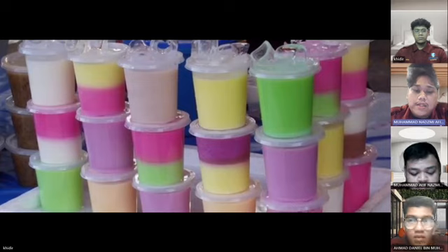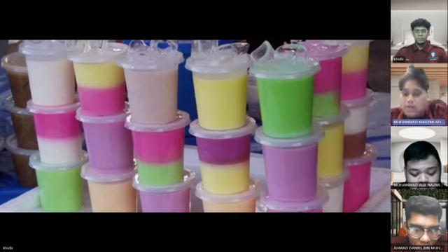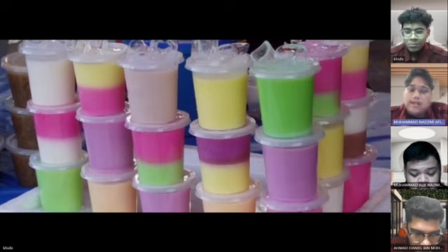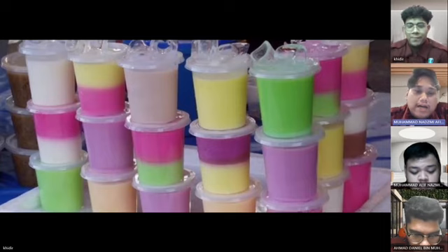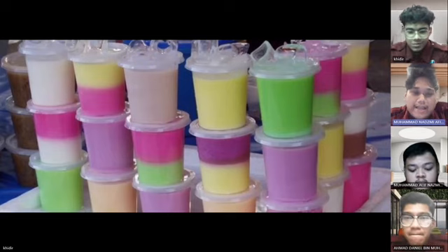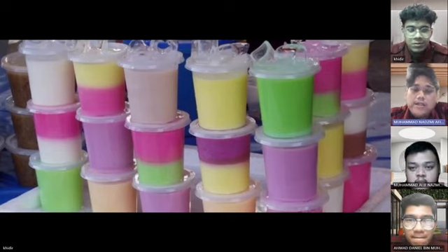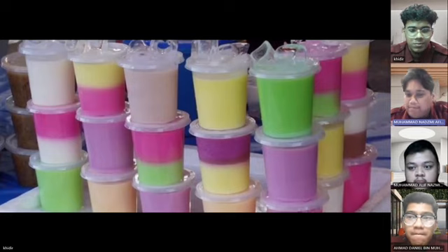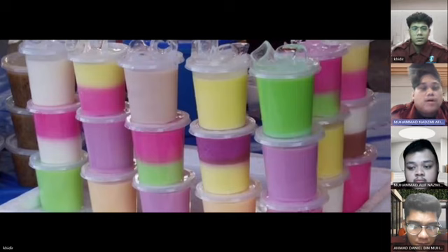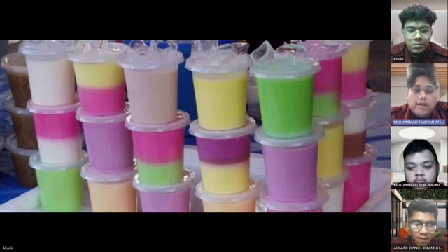As the quantity increases, the cost per part decreases. And the cost of this injection molding is a high initial investment. Making and setup for injection molding equipment is more expensive, so it's not ideal for low volume or short run manufacturing.